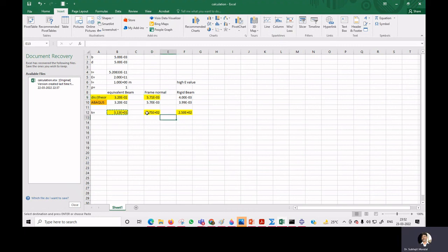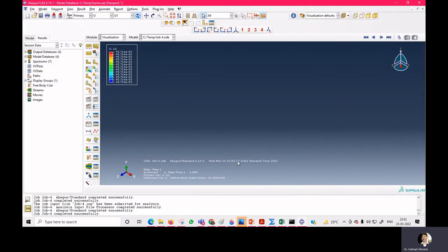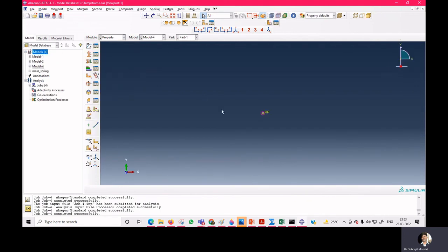So if you consider a mass spring system and provide the equivalent stiffness, we also get the same amount of displacement. If you have a very complex problem, in that case you can model it as a single degree of freedom system, and you can obtain your desired displacements or other quantities also.